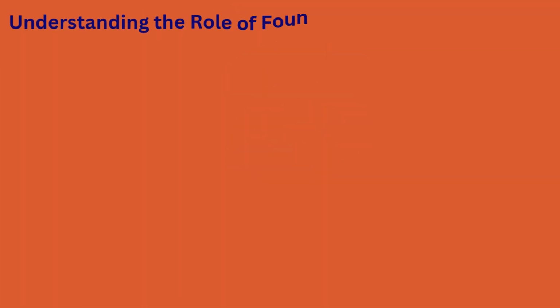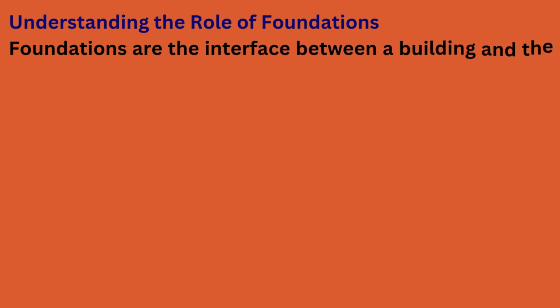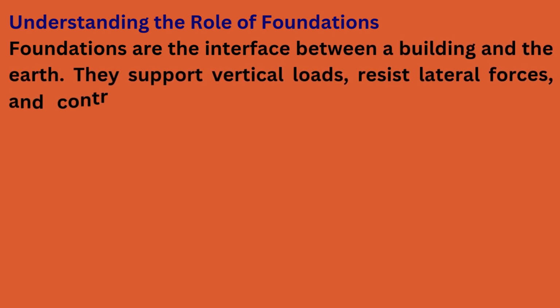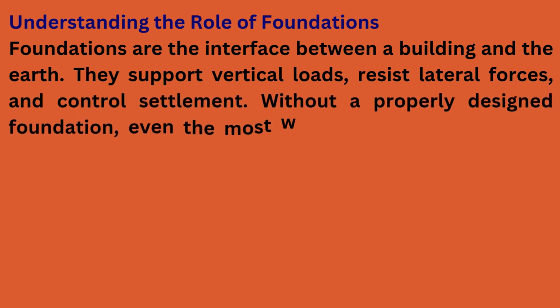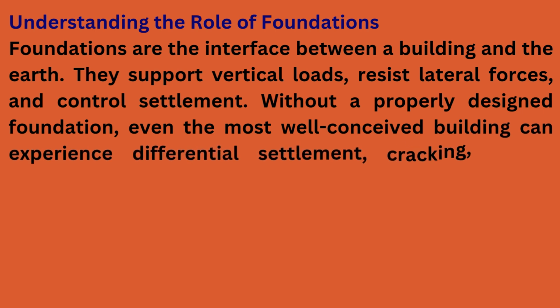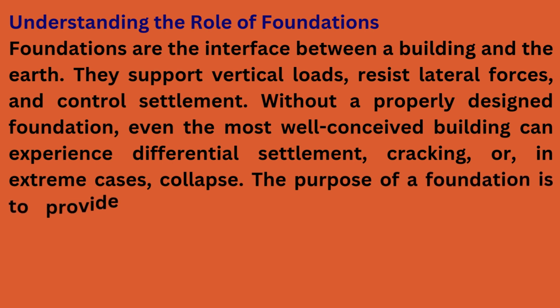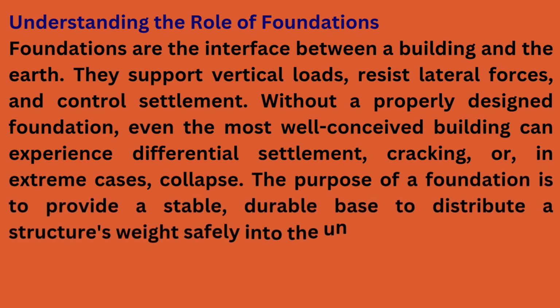Understanding the role of foundations. Foundations are the interface between a building and the earth. They support vertical loads, resist lateral forces, and control settlement. Without a properly designed foundation, even the most well-conceived building can experience differential settlement, cracking, or, in extreme cases, collapse. The purpose of a foundation is to provide a stable, durable base to distribute a structure's weight safely into the